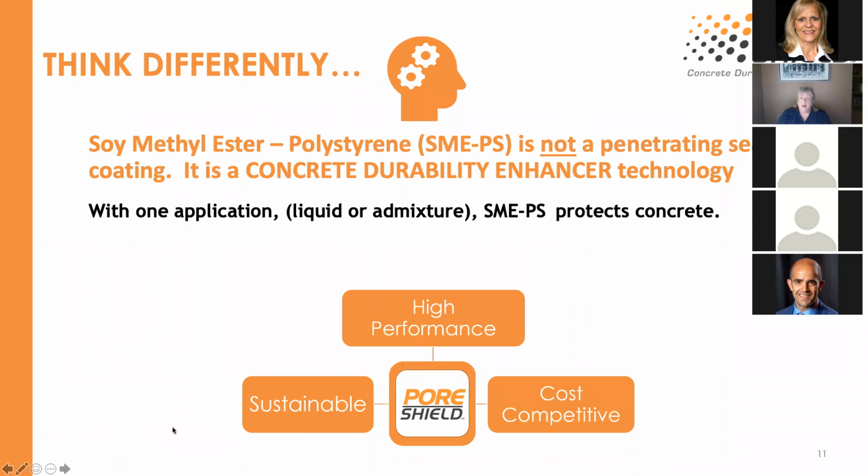So I've mentioned concrete durability enhancer, which is probably not terminology that you're really familiar with. We're asking you to think differently. It is a new category. The soy methyl ester polystyrene Pore Shield is not a penetrating sealer. It's not a coating. What it is, as we've said, is a concrete durability enhancer, and I'm going to describe to you why it's different in the next couple of slides. But with one application, whether it's in liquid form or in admixture, it protects concrete for 10 plus years.